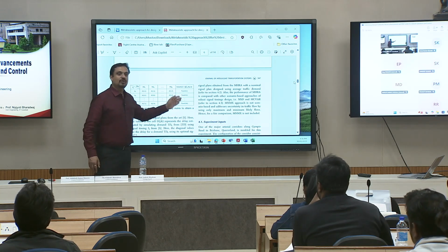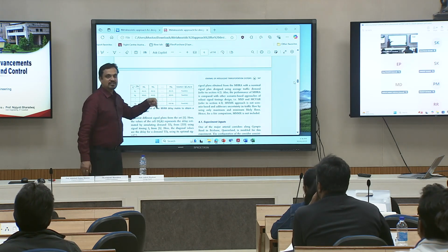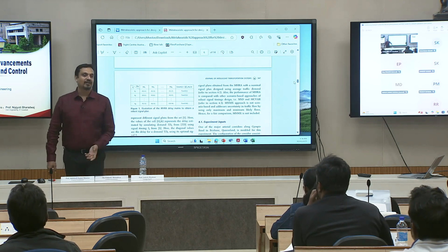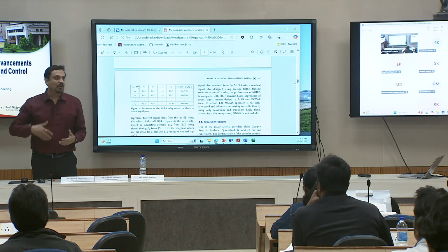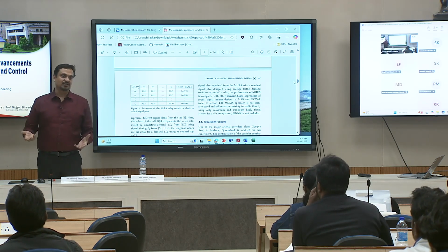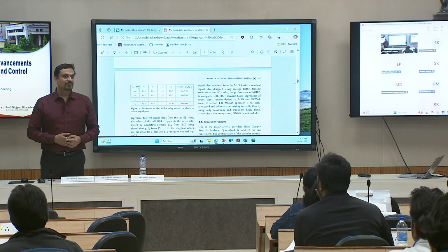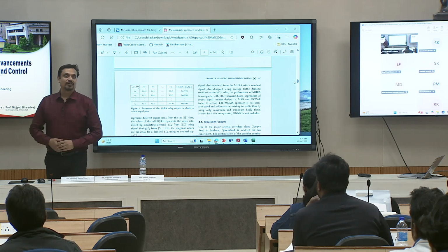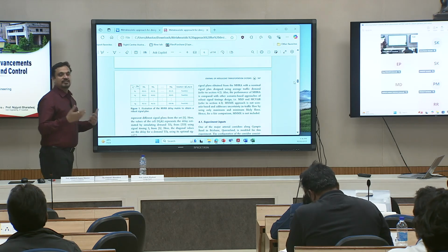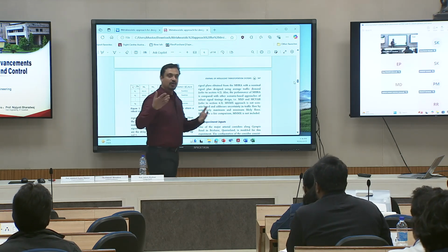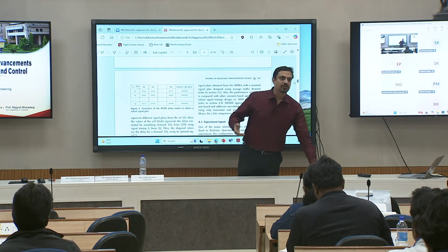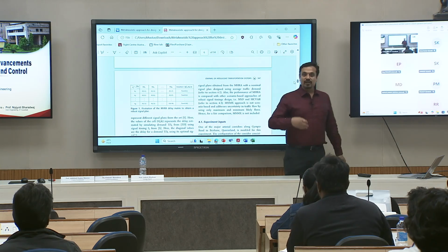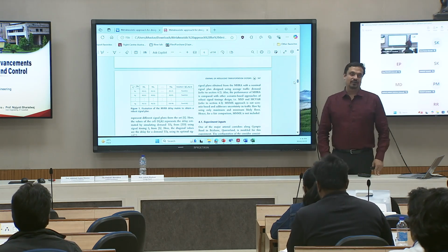Then you will say, I'm going to choose the one which gives me less variation and lower delay. That's the kind of decision you can make. You can run it for multiple ones and then make a decision. So that's one approach of doing that. You are using SIDRA analysis, or any other software tool you might be using, to do that optimization. You can even write your own code to do that.